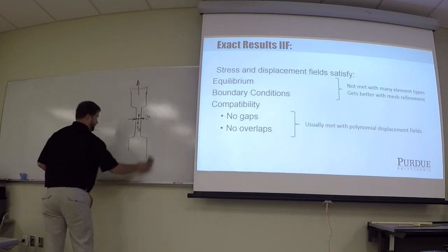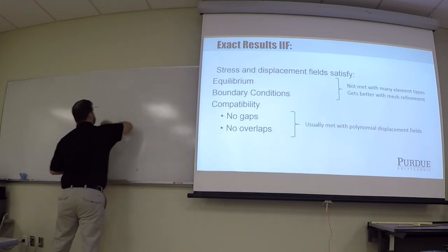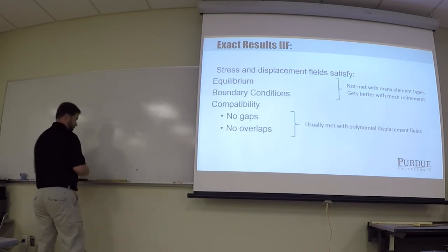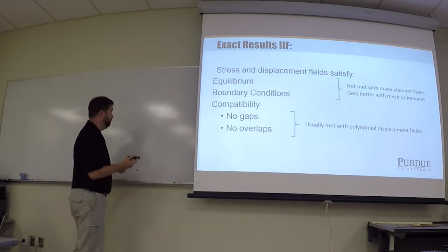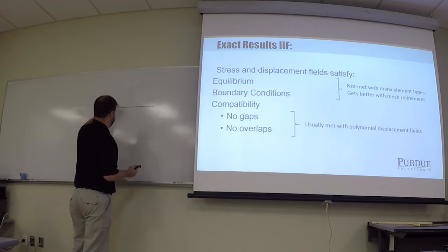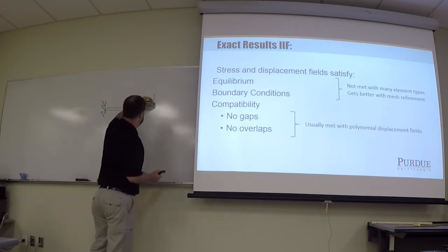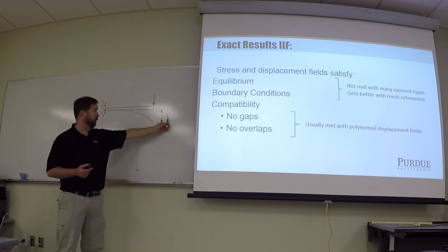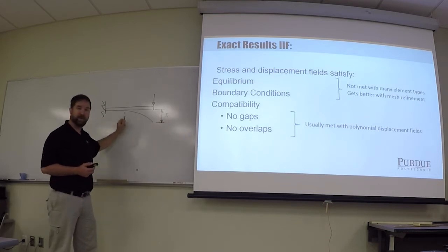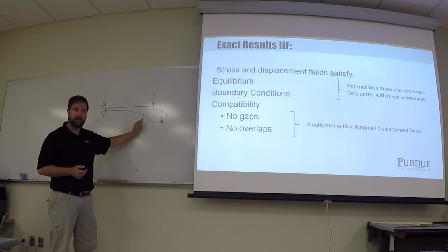Thinking about back to beams. If we did a tapered beam for the homeworks, but let's assume we just have a straight beam with a constant cross section, and I put a load on the end and I calculate what the deflection of that is. Right? We can do a hand calculation to come up with this deflection value. Right? I can also model this in SolidWorks using the weldments tools and so on that we've shown.